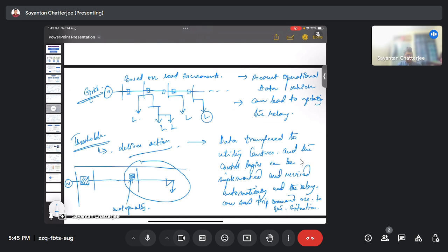Now this area, which was firstly a part of that area, a specific time is allotted for this relay to actuate for that fault. If this relay doesn't actuate for this fault after the stipulated amount of time that has been assigned, then these backup protection schemes also render the protection to that fault.